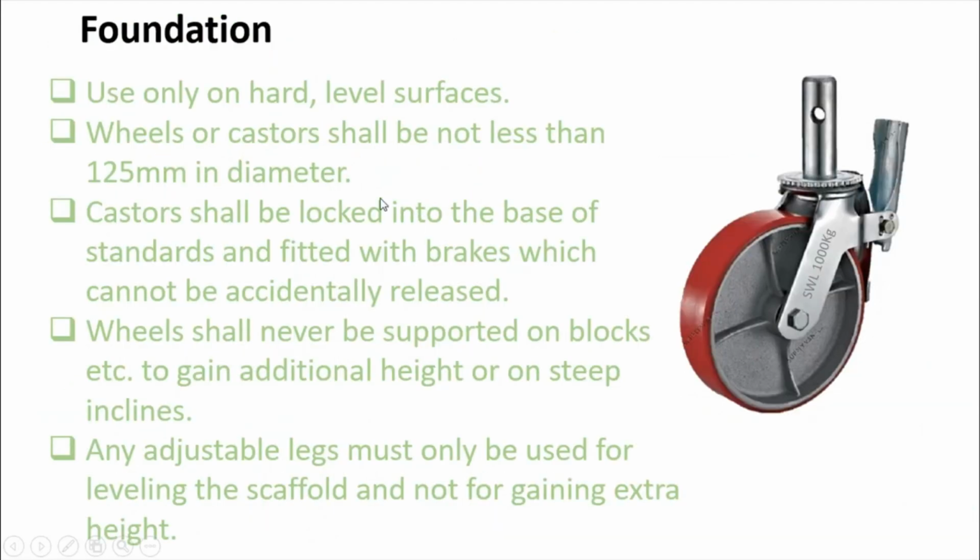Okay, so foundation: use only on hard level surface. So when you are using the mobile scaffold, you need to check the area is level, the surface is level and hard, fully compacted, to prevent the wheels sinking on the surface, because once it's sinking, the scaffolding will collapse or may tip over on the ground, so the stability is compromised.